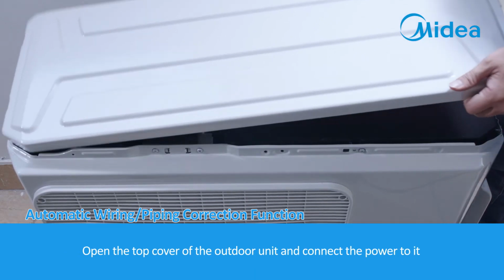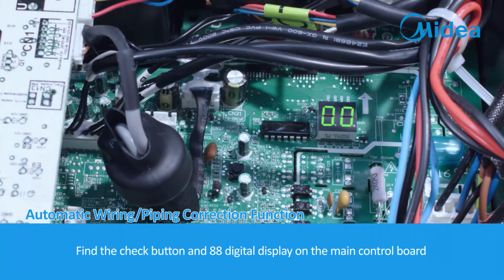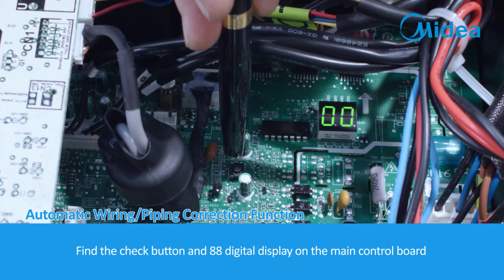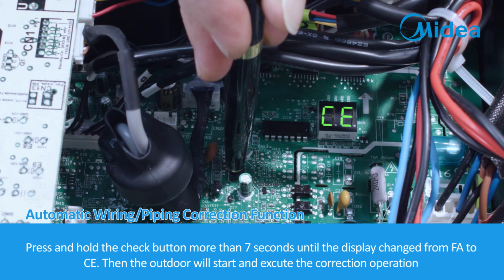Open the top cover of the outdoor unit and connect the power to it. Find the check button and 88 digital display on the main control board. Press and hold the check button more than 7 seconds until the display changed from FA to CE.